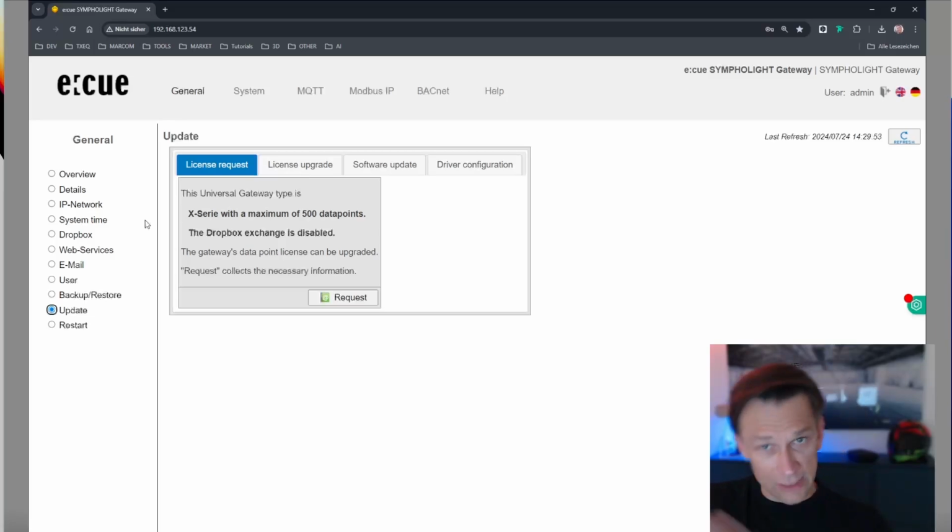In the opposite direction, these are other data points. Let's say you want to read out the information of the sequence, and this is one data point. You want to control the sequence with start-stop, so this is another object, and this is another data point. So in total, for one sequence, you would use 2 data points for status and control. The smallest version of the standard gateway comes with 25 data points, enough for, let's say, 10 sequences to start and stop.